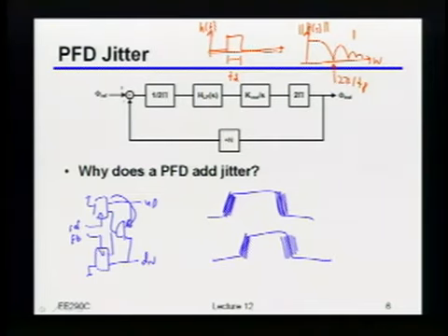Yeah, so basically what I'm saying is that, intuitively, you should already see why the bandwidth is proportional to 1 over TP, right? Because I'm doing this windowed integration. If I did a windowed integration for a longer period of time, I would have less bandwidth, right?